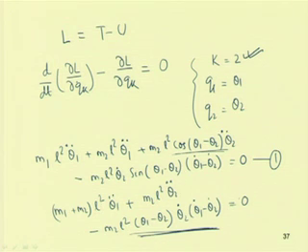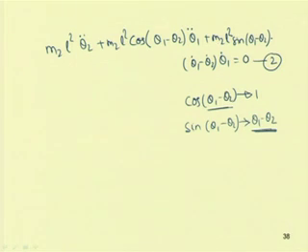or if one expands this cos and sin for higher harmonics, one can get quintic or higher order equations of motion also. So, this is for the first mass. Similarly, for the second mass one can expand sin(theta 1 minus theta 2) or cos(theta 1 minus theta 2) and write the nonlinear equation of motion.